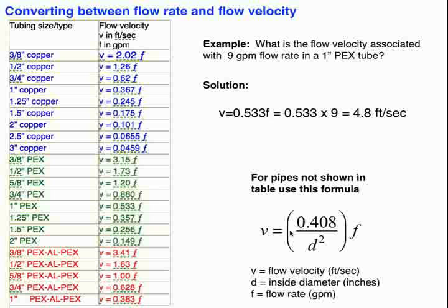Let's move on to talk about sizing a pipe. There are several issues that come into play here. One of those issues is air entrainment. If we move water extremely slow through a pipe, especially a pipe that's vertical where the flow is moving down, you can imagine that bubbles, especially larger bubbles, can actually move upward faster than the liquid is moving down. And we don't want that. In general, we want to be able to entrain air bubbles. We want to be able to drag them along with the liquid and eventually bring them back to an air separating device and capture them and eject them out of the system.